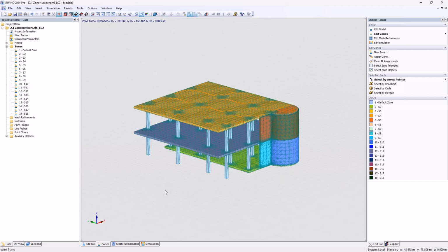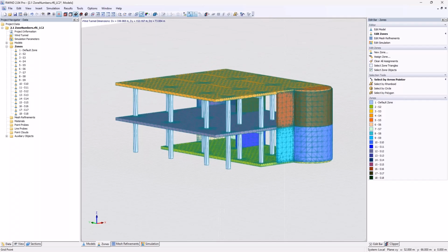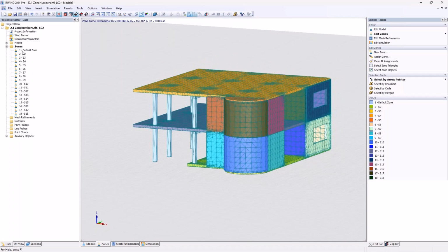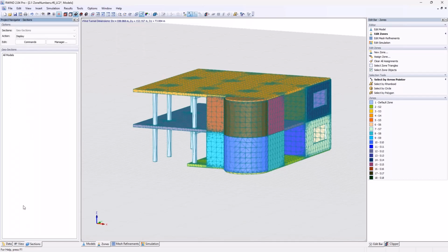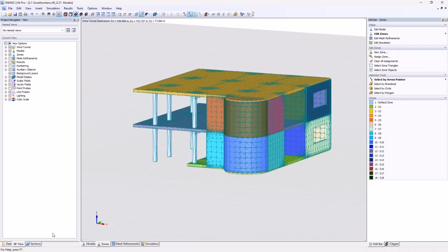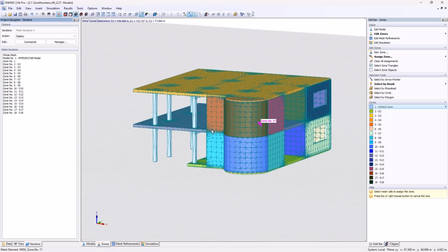Now, if you already consider the surface numbers or a certain division in RFEM 6, you can directly create these zones in order to quickly evaluate, maybe, normalized pressure over a certain zone. I will later on show you how we will use it on our monopitch roof. And as said, you can see that there's of course also the default zone number 1, where you will then be able to find every other item which is not related to a surface number.